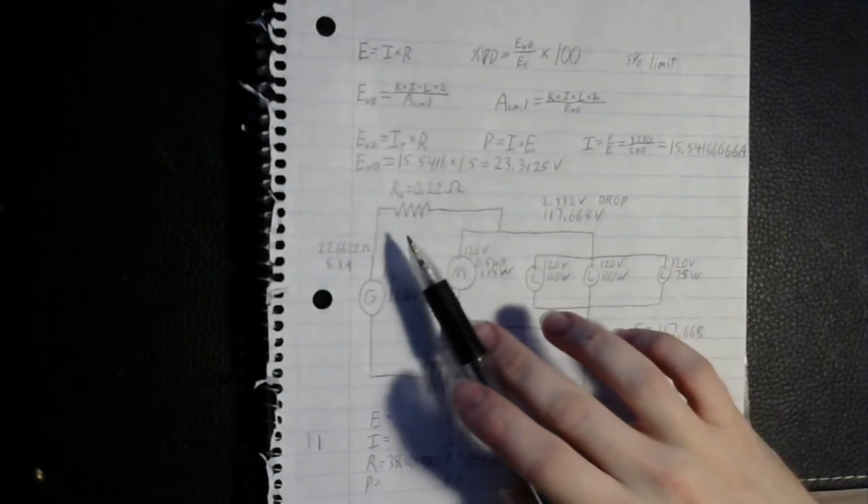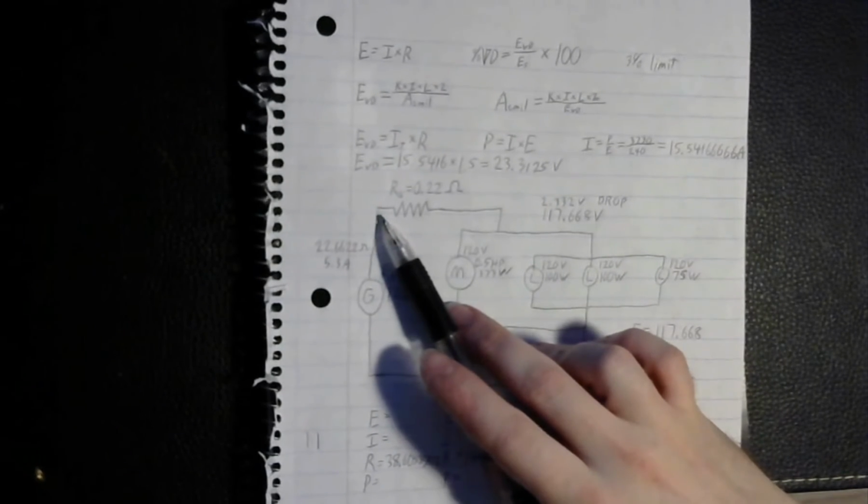So I have a question. It's probably dumb, probably something that's been reviewed. But with regards to the voltage drop affecting the load, wouldn't that only include the wire going to the load and not necessarily also from the load? If it were a DC circuit, yes, but we're dealing with AC circuits. So with an AC circuit, you need to take into account the wire both on the hot and the neutral side of your circuits. That's right, because it balances between both.